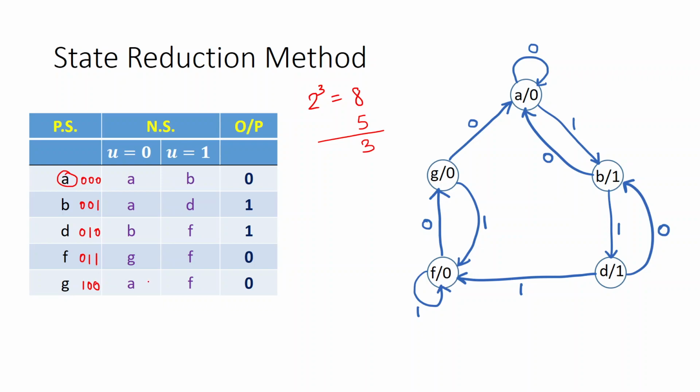However, we have to take a precaution, because sometimes during starting or during some malfunction, it might so happen that we land upon these states which are not used by the system. These states are not proper system states, right? So these are called the redundant states.